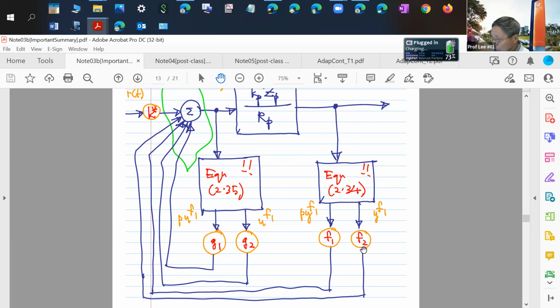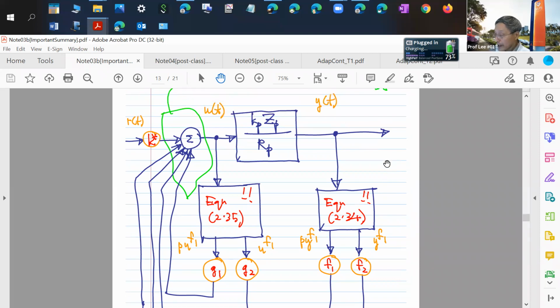Then in LabVIEW, you multiply by these gains. Then this is your reference signal you have. In LabVIEW, you multiply by this gain, and in LabVIEW, you sum this up and put this in. This exactly realizes for you your perfect control law. So certainly this is clearly realizable. And clearly these numbers exist, because if you knew the system perfectly, you can calculate out these numbers, and these numbers exist. Then remember what we said.